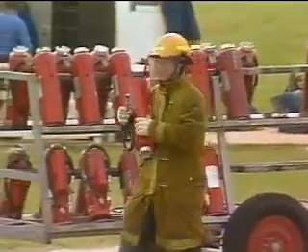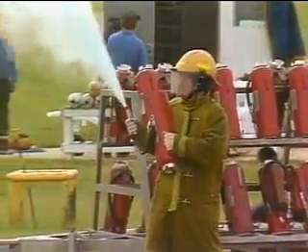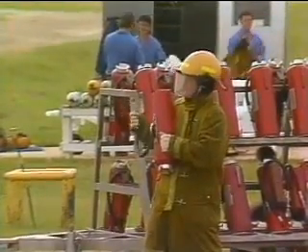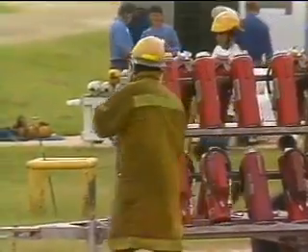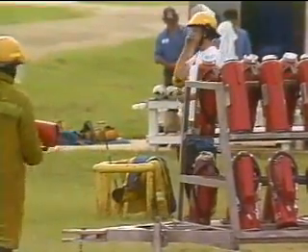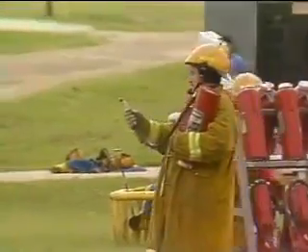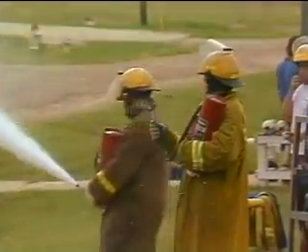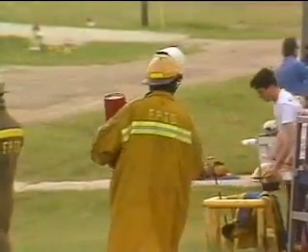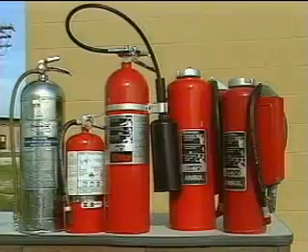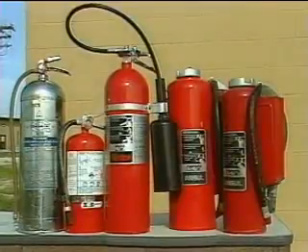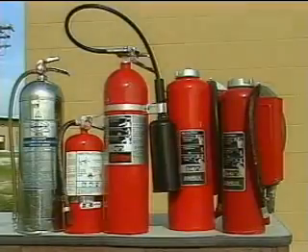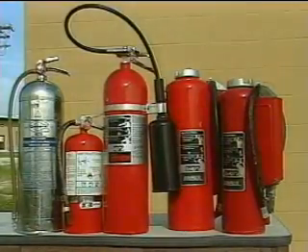Also, after the initial duration of effective spray, the extinguisher may continue to spray. However, this additional spray does not contain any firefighting agent and is useless. When this occurs, you can hear the difference because the extinguisher is simply gassing itself off. This is a much hollower spraying sound than when the agent is being delivered from the extinguisher. Before we explain proper handling techniques, we first need to look at the various types of extinguishers available and their applications.